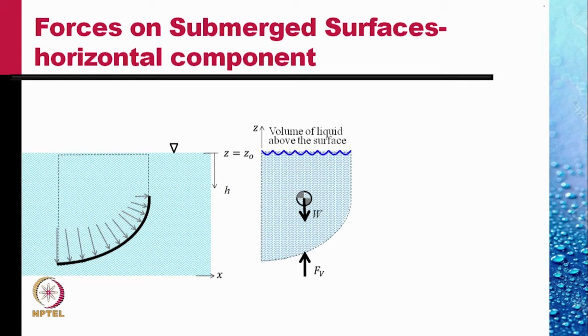If Fy is the vertical force acting on the plate because of the liquid, then on this free body of liquid, there is a force due to the plate equal to Fy acting upwards, the reaction to the force on the plate by the liquid. The only other vertical force on this free body is the weight of that liquid resting above the plate up to the free surface.